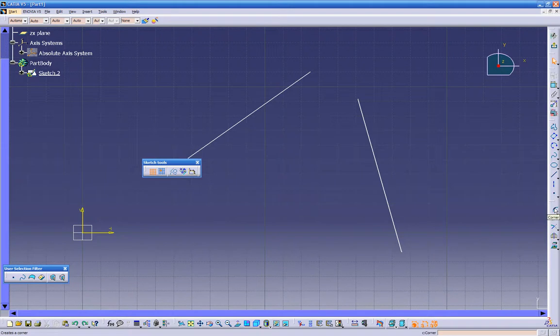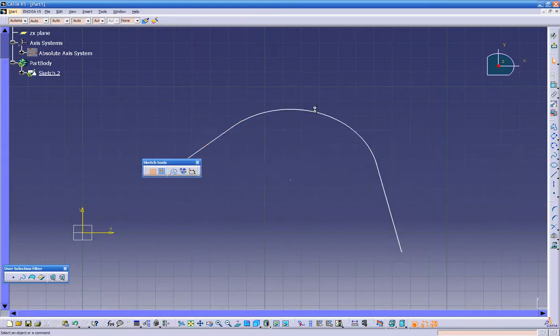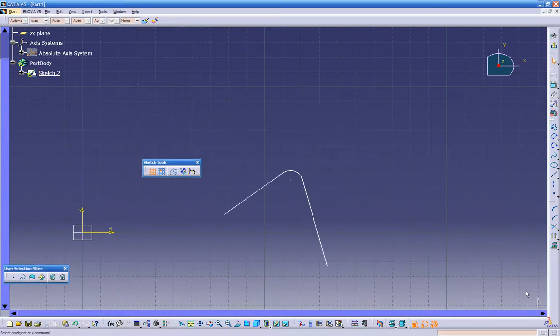on the corner icon. As you see, you have different kinds of radiuses you can create. Click on line number 1, number 2. You can put it anywhere you want, but you can go back anytime later on. Just double click on the corner radius, and down here we can change it to 0.250. See, that's the difference. If we do that, it moves the line. So if we do Control Z, we can undo it, and we can do right click